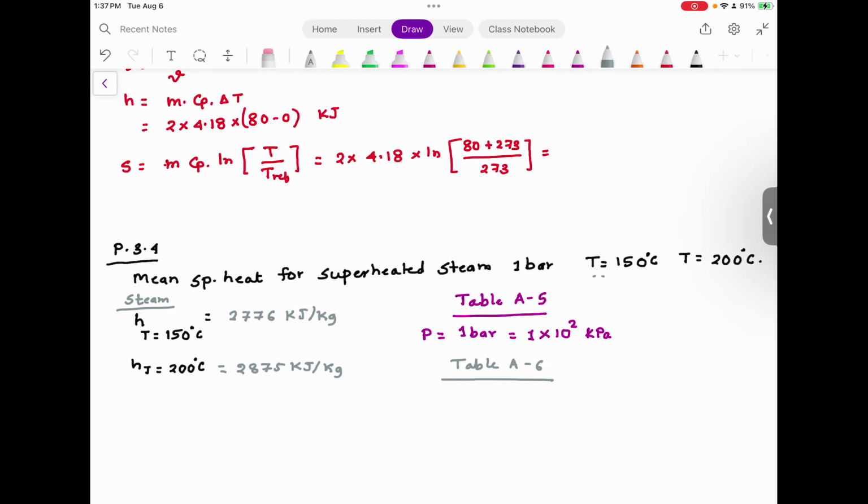Are you able to track it? You may need a magnifying glass, but you should be able to track it. I can quickly show you. So 150 degrees, go horizontal, and then you will notice these lines. These are the bars. You see 10, and then you get all the way over here to 1. And then if you draw the horizontal line, that is where you see the enthalpy scale.